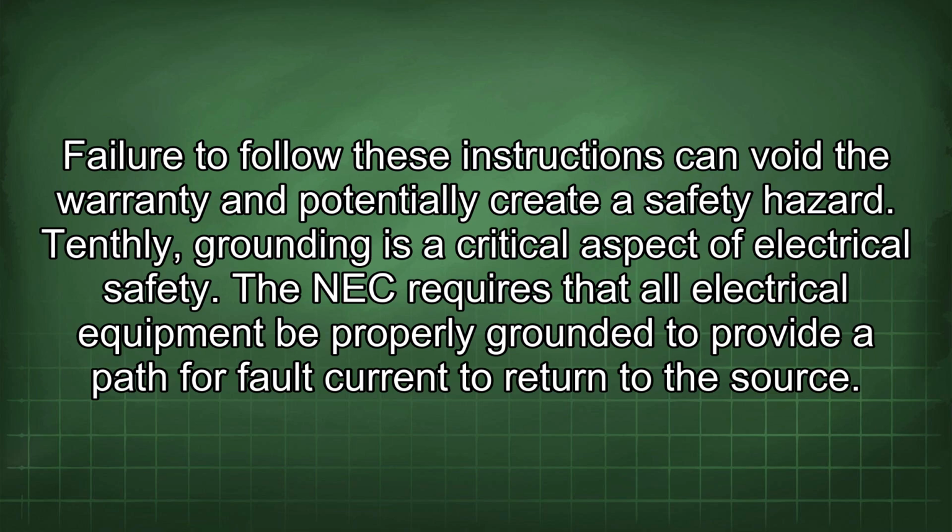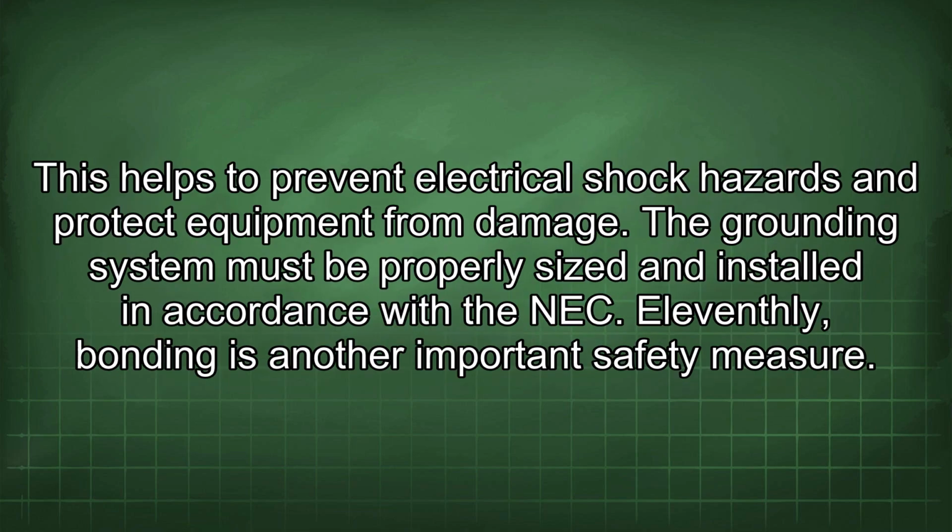Tenthly, grounding is a critical aspect of electrical safety. The NEC requires that all electrical equipment be properly grounded to provide a path for fault current to return to the source. This helps to prevent electrical shock hazards and protect equipment from damage. The grounding system must be properly sized and installed in accordance with the NEC.